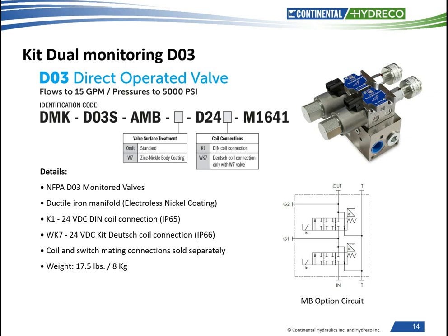In the series circuit, you must actuate both valves to allow pressure and flow to reach the outlet port. So as we're looking at the schematic, on the inlet, you must energize the very first valve in order to allow flow and pressure to continue on downstream to the second valve. When that valve energizes, the switch changes state. In order to get flow to the outlet, the second valve must be energized. The signal will change state. Now flow and pressure can continue on to the outlet port off to your system.